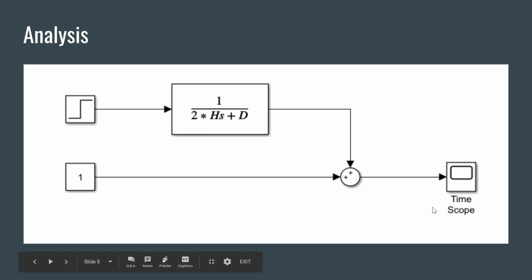After evaluating the poles and zeros of the transfer function, the open loop plant is BIBO stable by itself. This is mathematically confirmed by the open loop transfer function having a pole at negative 1/8 with H equals 4 and D equals 1. The open loop system is modeled with the load power being modeled by step functions.